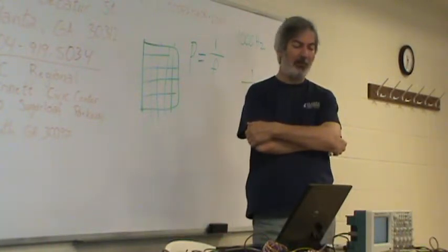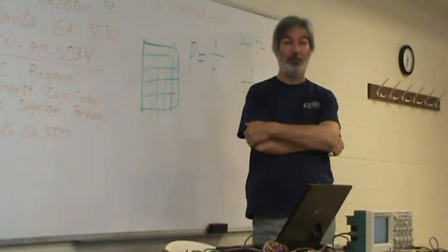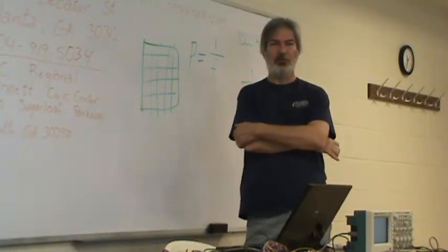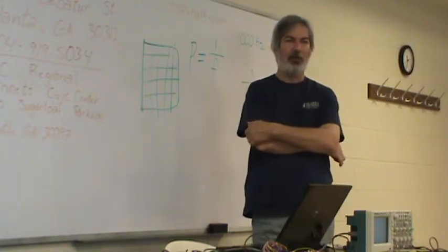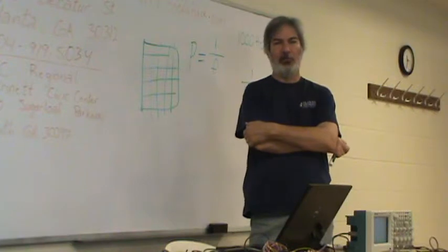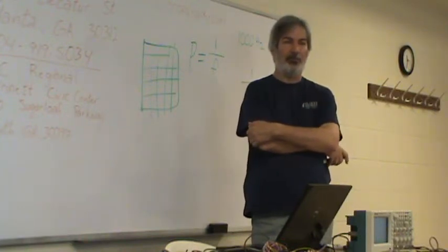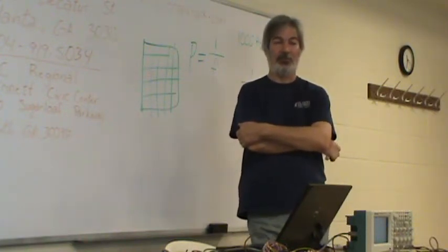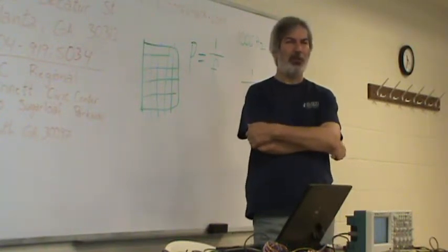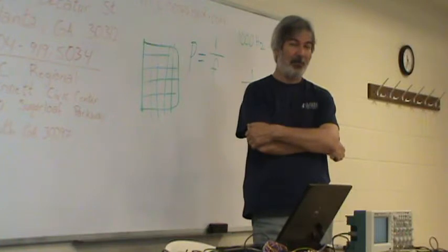Hopefully by the time you've got things together to the point where you've got your scope going and you're trying to diagnose what's wrong, you should generally have an idea within your circuit of what to expect where. There may be some places where you've got some signal that is just completely unknown. But most of the time, you should have a pretty good idea of what to expect.